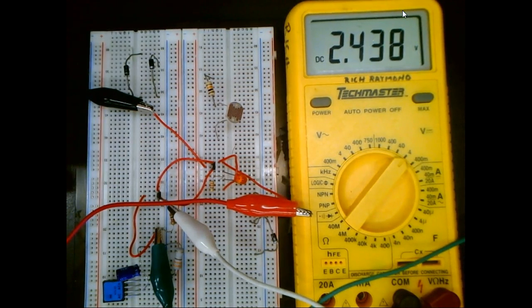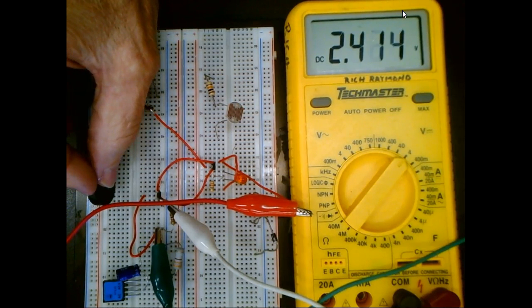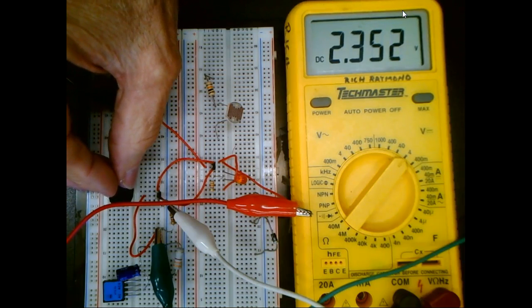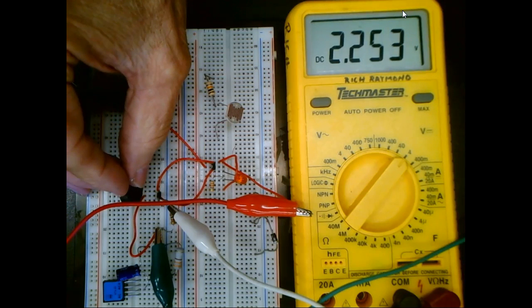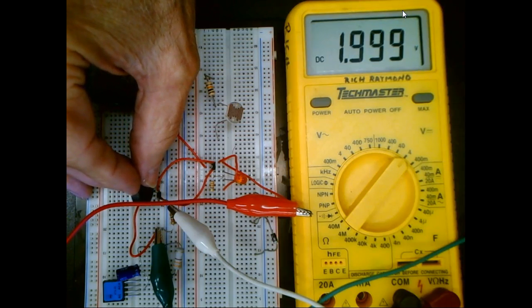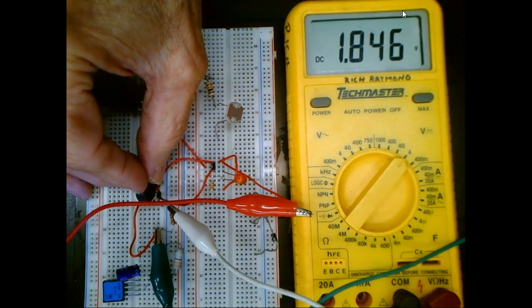So here's my magnet, and this is a linear sensor. So I'm going to start bringing my magnet in toward it. Notice right off the bat, the voltage drop across my resistor or my load is going down. And the closer I get to it, the magnetic field is getting stronger, right? So as the magnetic field is getting stronger, its output voltage goes down.